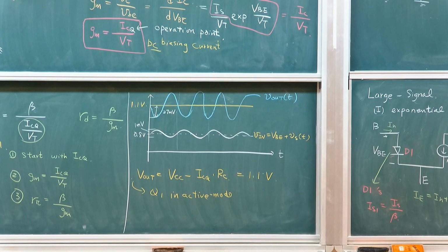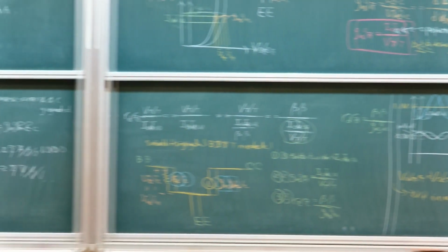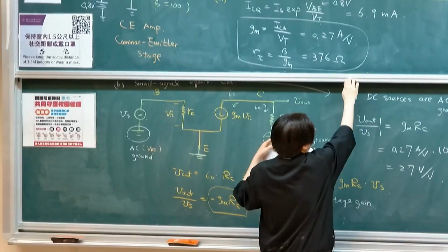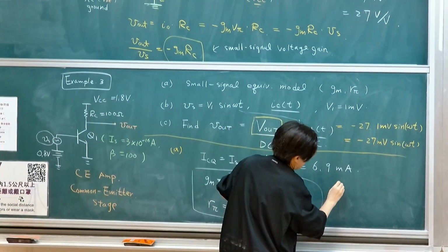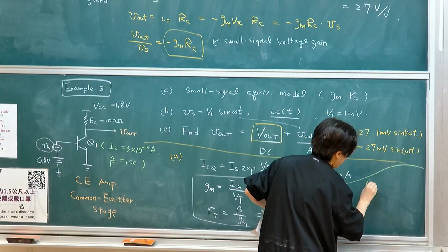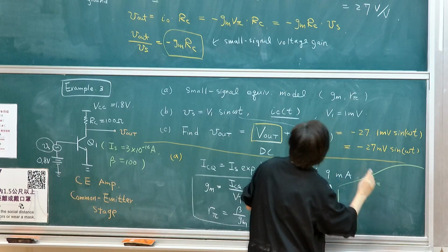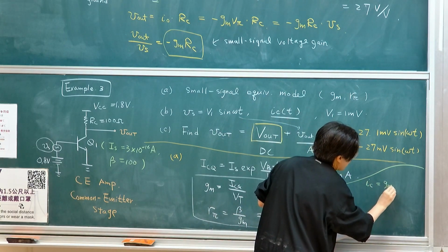Okay? Good? Any questions? We still have a little time. Did I miss something? Oh, IC. I didn't get the IC. I should say this. IC is fairly straightforward, it's this, right? So IC, let me just write it down here. Your small signal ic will simply be gm v pi.